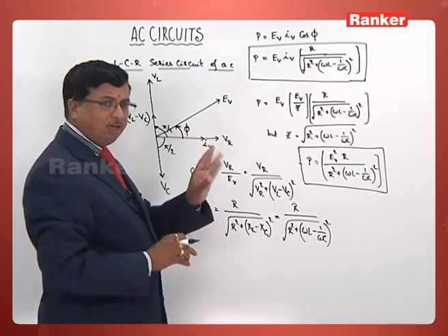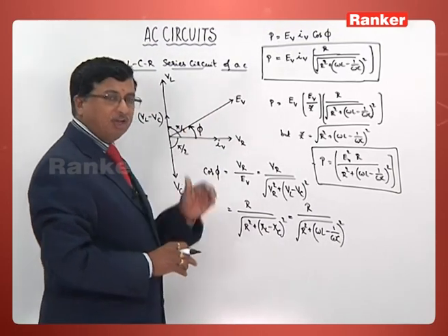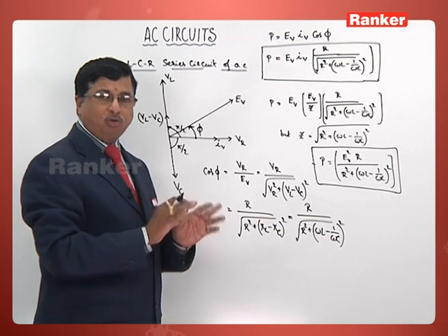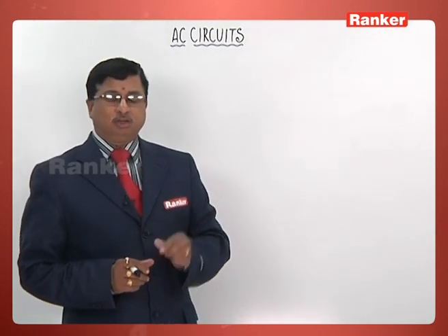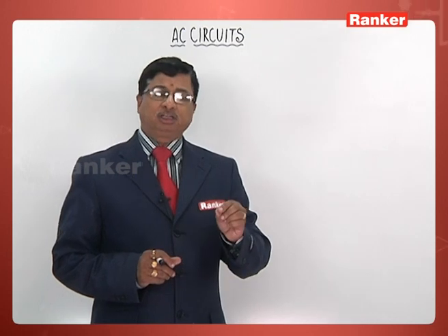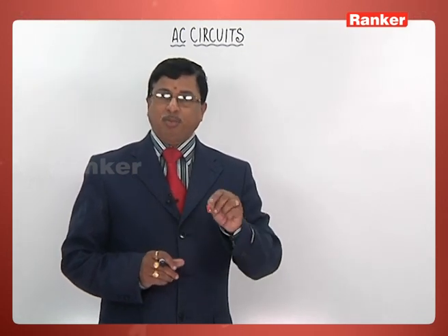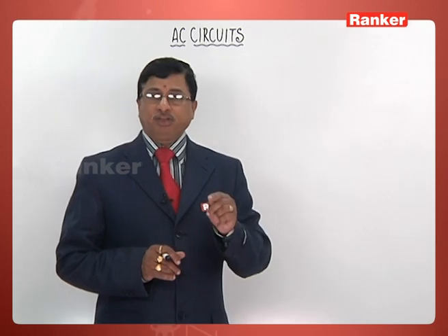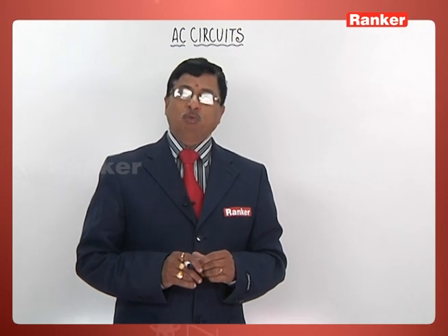So, as far as electric power is concerned, we have discussed how to calculate the values in an LCR circuit, in an LR circuit, and even in a CR circuit. Now, whenever an LCR circuit is in resonance, as we have discussed earlier, the total circuit becomes resistive at that time, and numerically inductive reactance XL and capacitive reactance XC are equal. As for the frequency, the angular frequency of that LCR circuit is omega equal to 1 by root LC.